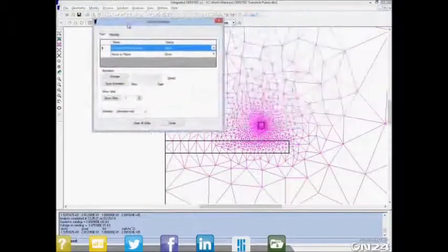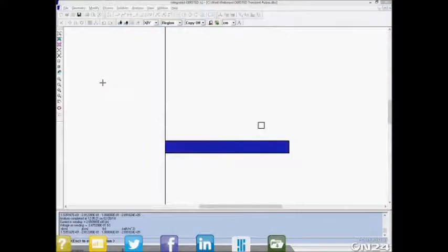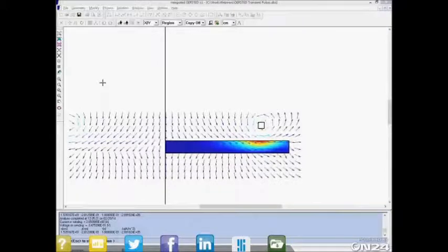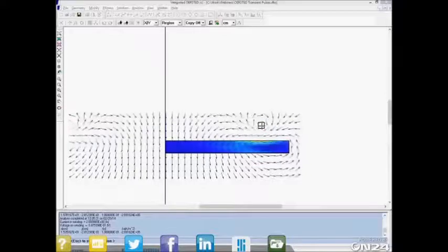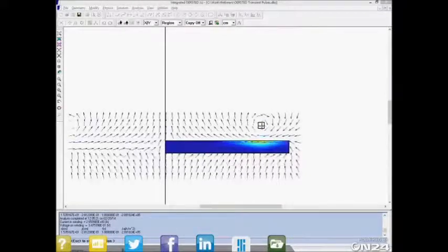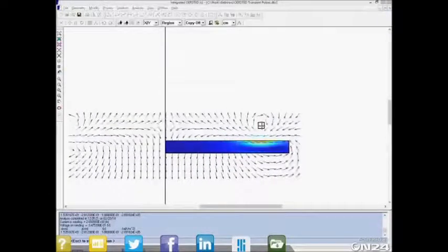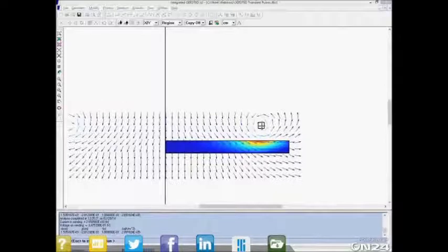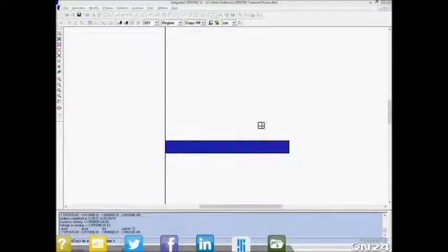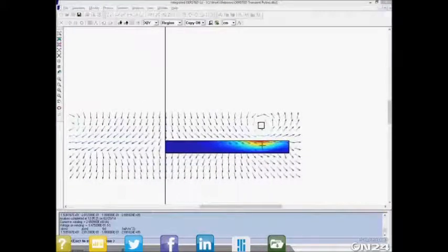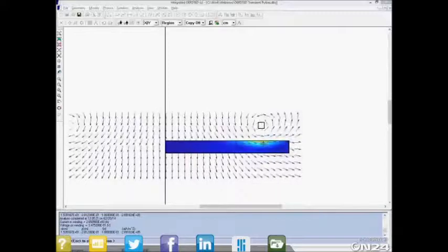So having run the model then, we can look at an animation of the B field and the J field. And what you'll see here is that the arrows representing the direction of the magnetic field line flux keep alternating because the current is going to flow positive and then negative through the coil as the voltage keeps alternating. And you'll notice that it's not an instant on-off, just like the current that's induced in the plate isn't an instant on-off. There are some time lags involved.